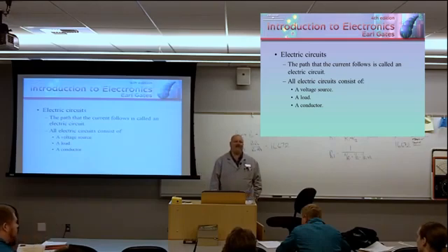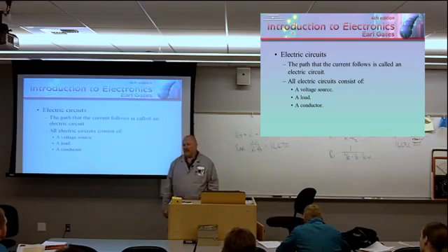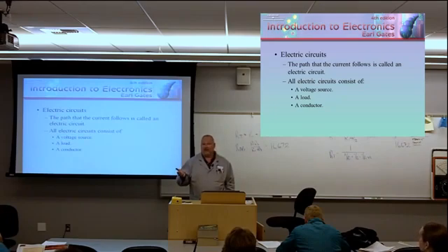But always go back to basics. Okay, God forbid you get out of class tonight, go out to your car out in the north parking lot, turn the key, and you've got an electrical problem. If you do have an electrical problem, approach it like this. Do I have a good source? Is my load functional? Is it the interconnects? Can I prove that the interconnects are viable? Is it a controlling device? And to be honest with you, in this day and age, most of the problems we encounter are controlling devices.